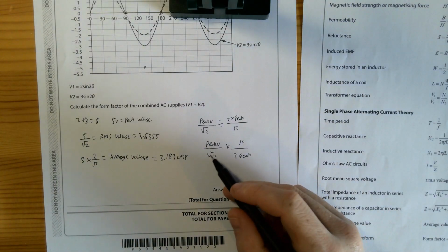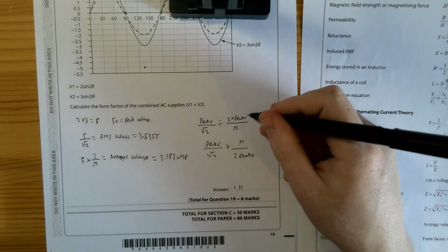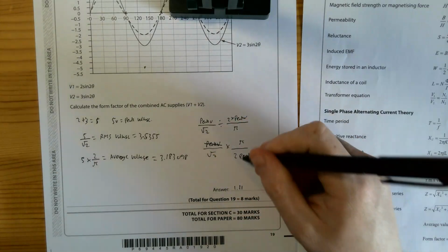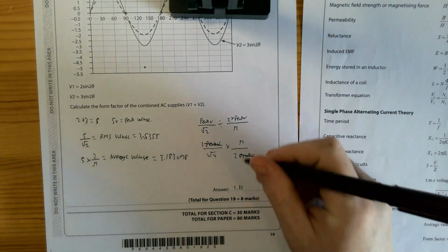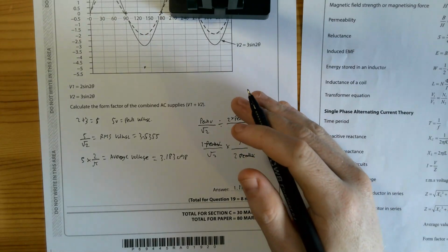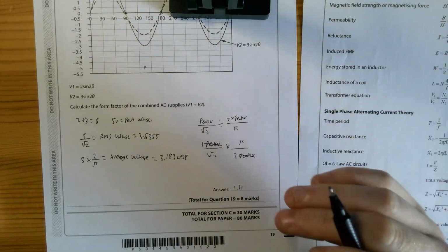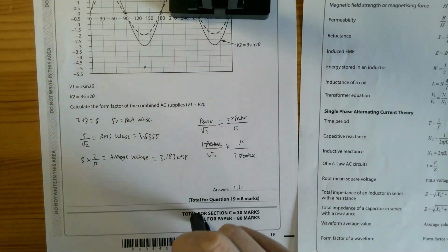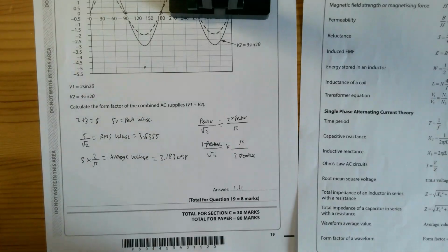Now what you can do is, if you've got any like terms on diagonals, you can eliminate them. I've got peak V and I've got peak V. They're on diagonal terms, therefore I can eliminate them. This then becomes a formula of 1 over root 2 times by pi over 2. If you plug that into your calculator, you'll get a value of 1.1107, so on and so forth. Okay, hence why the second I saw the form factor, I immediately knew it was 1.11. Okay. In other words, this question here is just a proof question. All right, you should know the value going into your exam.